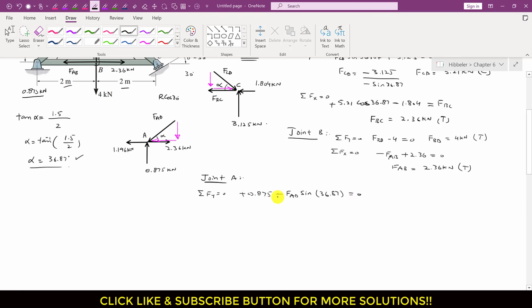So from this we can write that FAD sine of 36.87 is equal to 0.875. So FAD is equal to 1.46 kilonewton, and since it is acting towards this joint A, this is compressive force.